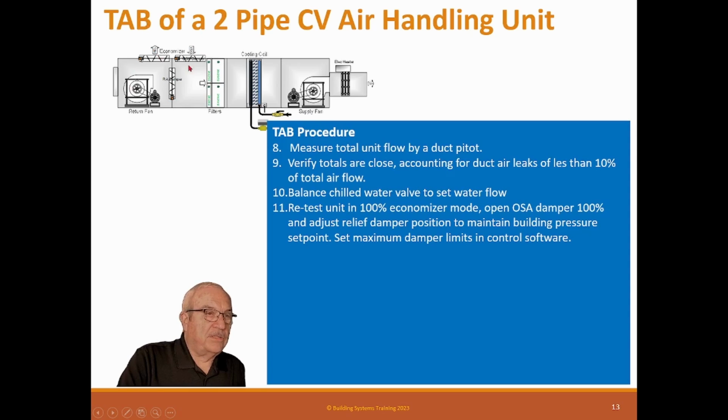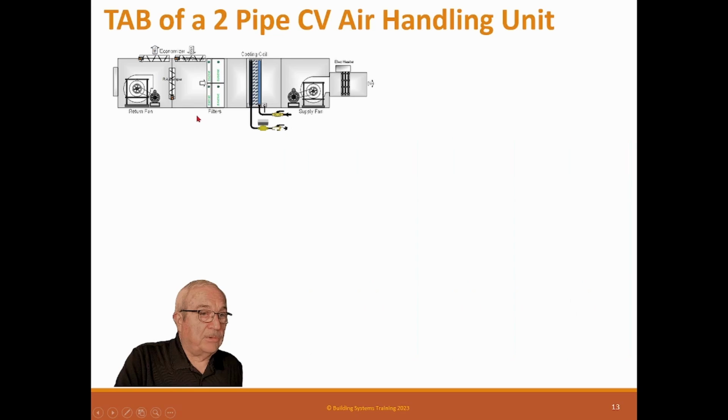And this is open, so it's sucking air in, and we're cooling the building with this outside air. But during that condition, we need to have the same building pressure we had in normal operation. So what we're having them do is adjust this damper down when we're in economizer mode. Now, if this has automatic control for building pressure, let me go check. I can't remember what this had.